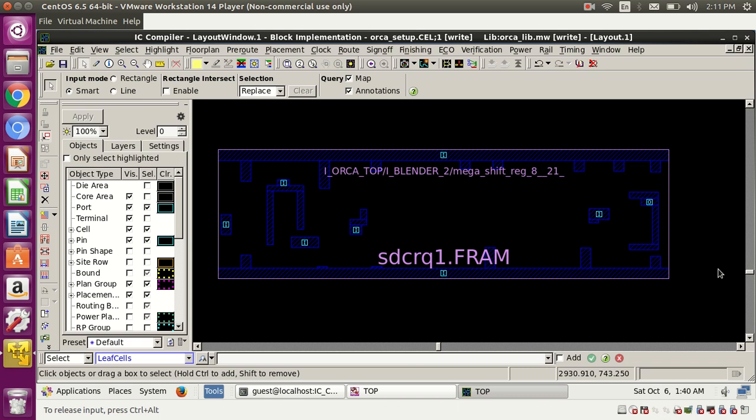Theoretically, whenever the clock rises, some hold time will be there. Suppose the clock is coming at 1 ps of delay, and the library hold time is 1 ps. Then the data should come at 2 ps only. Before that, if it changes, hold violates. By default the data is coming at 2 ps, so hold is not violating.